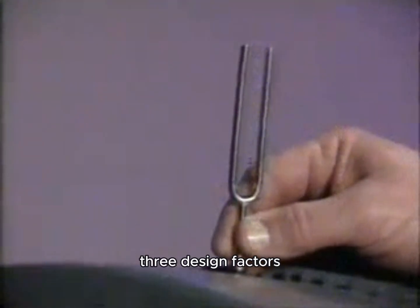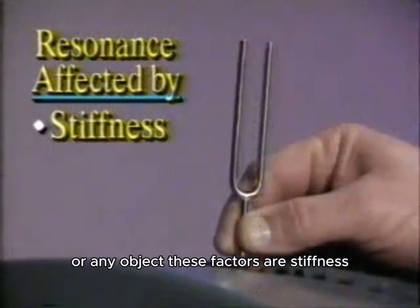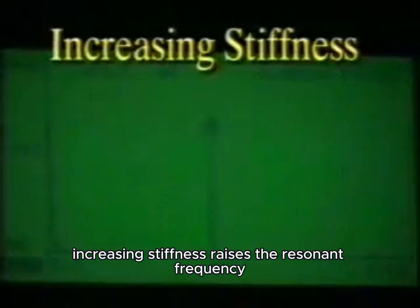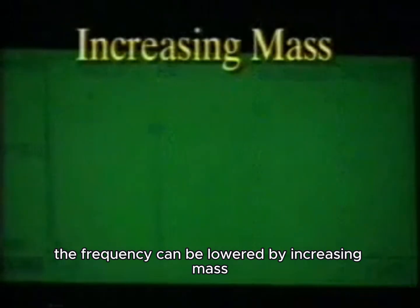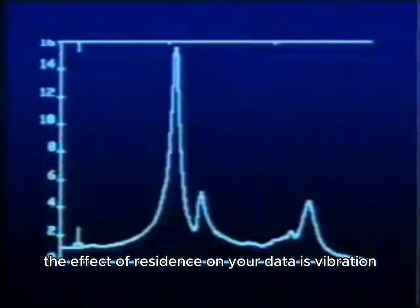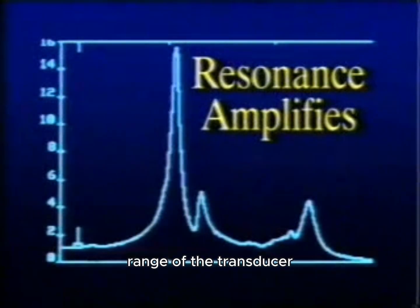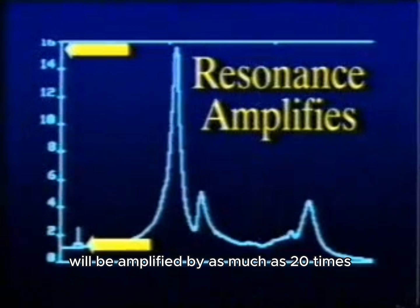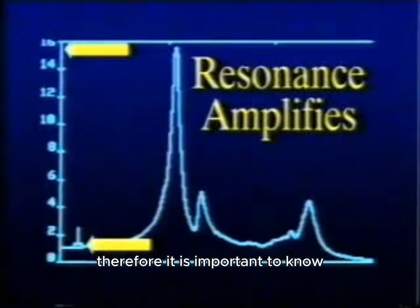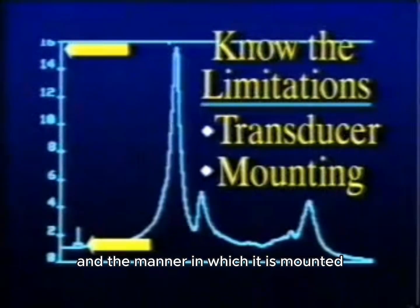Three design factors affect the resonant frequency of this tuning fork or any object. These factors are stiffness, mass, and damping. Increasing stiffness raises the resonant frequency. On the other hand, the frequency can be lowered by increasing mass. Finally, adding damping reduces the amplitude with little frequency change. The effect of resonance on your data is that vibration frequencies that occur in the resonant frequency range of the transducer will be amplified by as much as 20 times. Therefore, it is important to know the limitations of the selected transducer and the manner in which it is mounted.